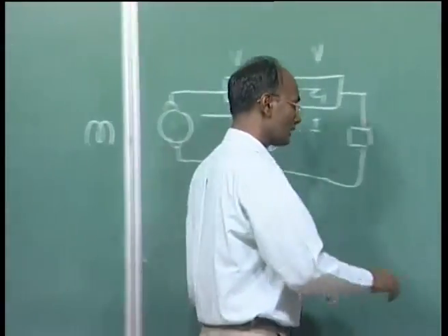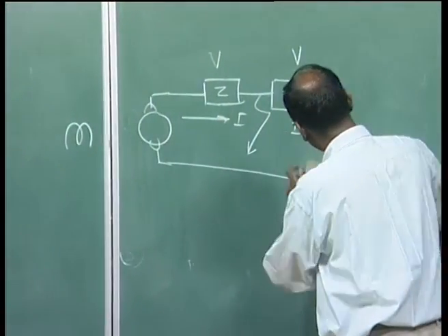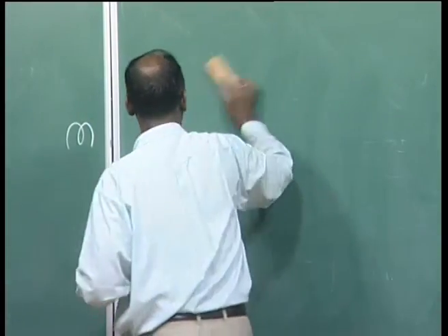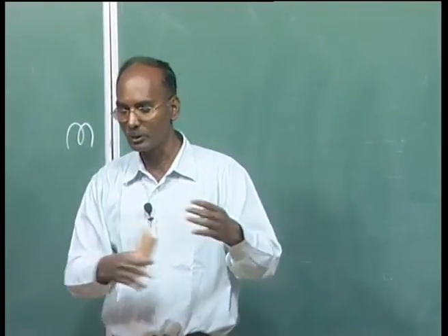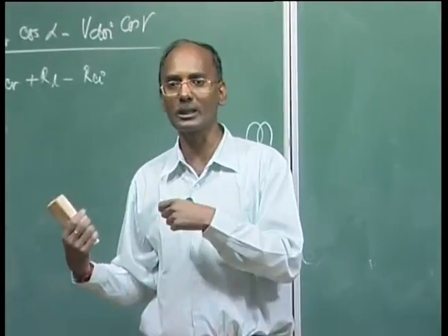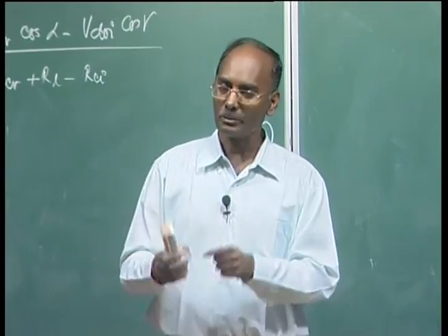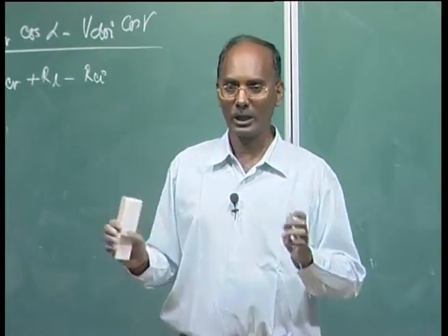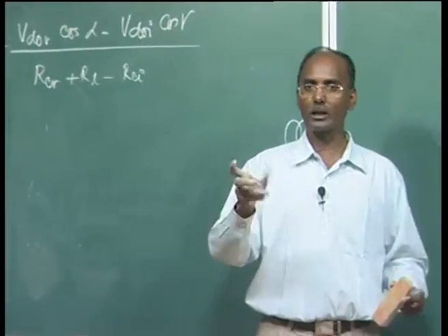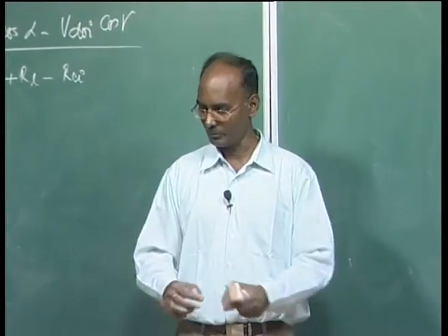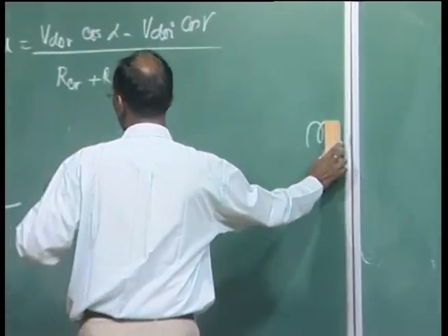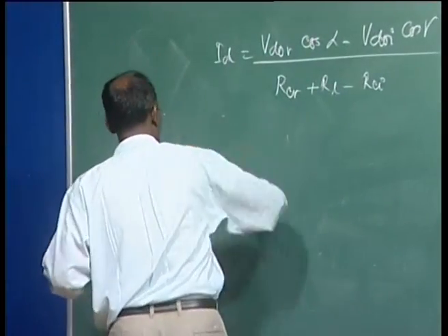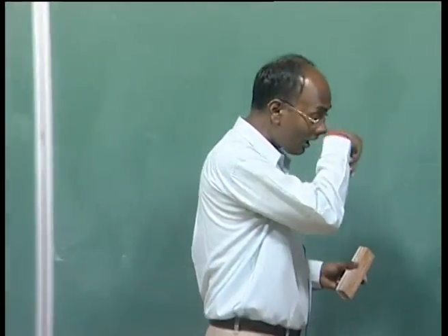My intention was not to explain much here, because I explained that if you are operating at constant voltage or constant current, how much you are going to get, meaning what the efficiency of the system is, and why we are using constant current in the DC system. The main reason is that we don't have a circuit breaker. Only our converter should act, and that's why we require the controller that will work just like a fault protection of your system. So now let us see, and we have to derive the characteristic one by one.